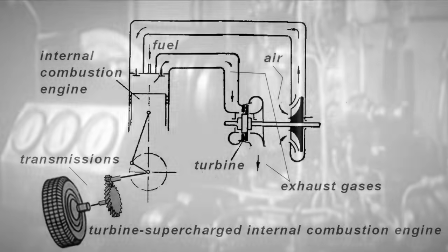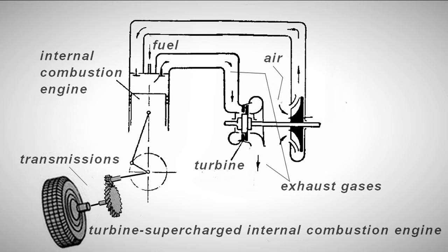While considering the pros and cons of the two engine types, engineers came up with the idea of combining them to complement each other. Calculations showed that by increasing the engine intake air boost pressure to 5 to 6 bar, the power of the compressor and turbine would be approximately equal to the power developed by the engine. Thus, the roles of the engine and turbine could be reversed. By decoupling the compressor and turbine, it would be possible to achieve a situation where the engine drives the compressor, while the turbine would serve as the power source for the payload.